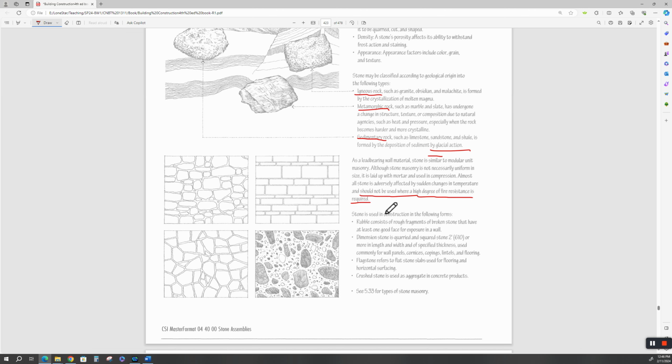Again, I go back. The labor cost in putting a stone wall up, I will bet you, if you do a cost comparison, you'll find you could have gotten a good CMU reinforced wall with a brick veneer, if you didn't want to look at the ugly CMUs, a lot cheaper than you will stone. And a lot of stone is cut thin and just used as a veneer.